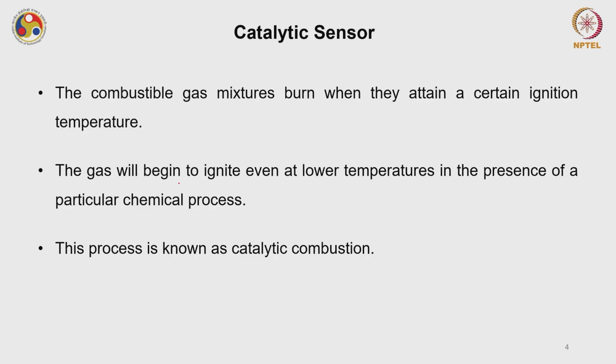Okay, usually catalysts were used in these catalytic sensors to bring down the temperature of explosion for these gases at trace level. Okay, so for example, if I have 1% hydrogen, or say 1% methane, CH4, it catches fire at say 400 degrees Celsius.